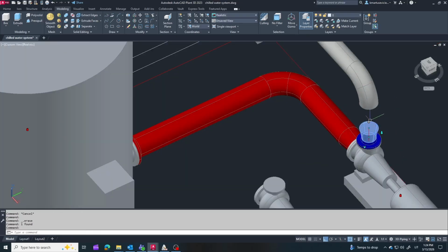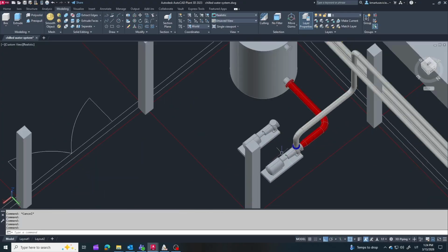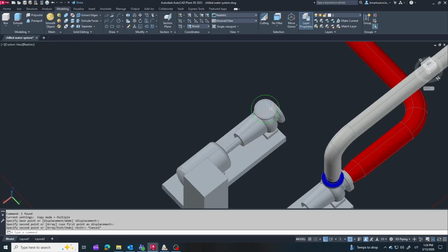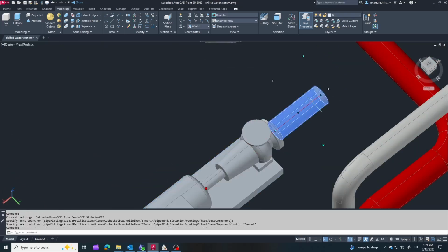Also pay attention to the pump nozzles and nearby piping. Both the suction and discharge pipes should be properly supported close to the pump nozzles, so the pump is not loaded by the weight of the piping or by thermal and mechanical stresses.